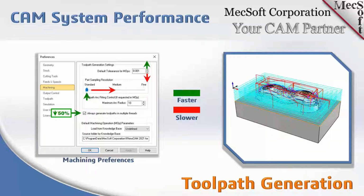And actually, Joe, in the tests that I performed, I didn't see a whole lot of decrease in time in going to the fine. It did some, but it wasn't so drastic that I need to stay away from fine. It's a linear decrease, so it's not that significant. When I say linear, it's not quadratic or exponential. So you would see some decrease if you go to fine, but not too much. And then at the top here, you can set your default operation tolerance for all of your operations, and that's set at 1,000 by default.